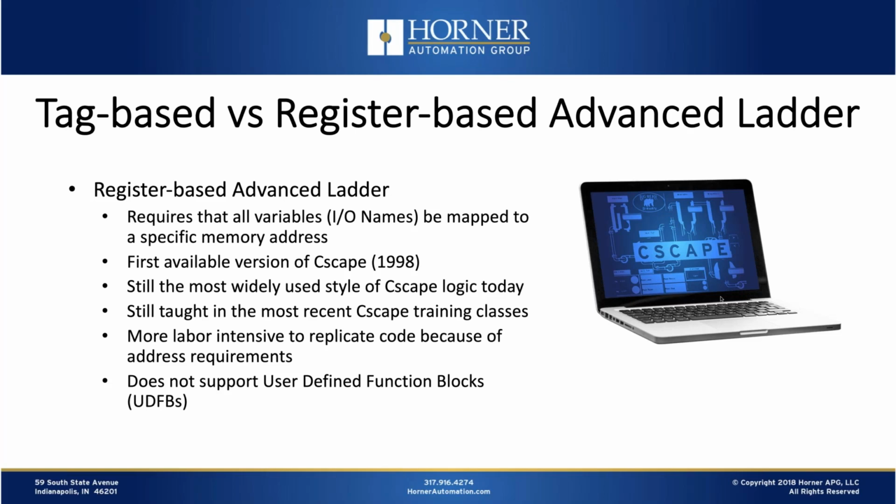So if you have a section of code that you want to replicate within your logic, because let's say you have multiple pumps that you want to control and the logic is basically the same, you can certainly copy and paste your logic. That's not a problem. But after pasting, you do have to manually readdress the pasted portion of the code for it to work properly, and that's extra work. And so that's one of the reasons why a tag-based approach, which we'll talk about in a second, is more popular, or at least more flexible in that regard.